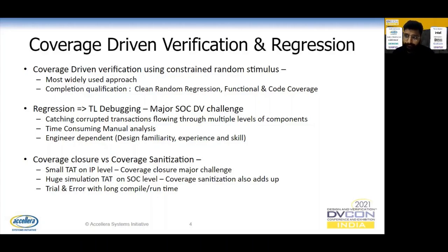it not only has coverage closure as a major factor, but coverage code sanity also becomes a challenge at SoC level test cases. As SoC level simulations basically involve long compilation and simulation time from a few hours to over a few days. And if I have to fix code and retry my fix, I'll have to wait for hours to get the results to see if my fix is really working or not. It may sometimes include a number of iterations.